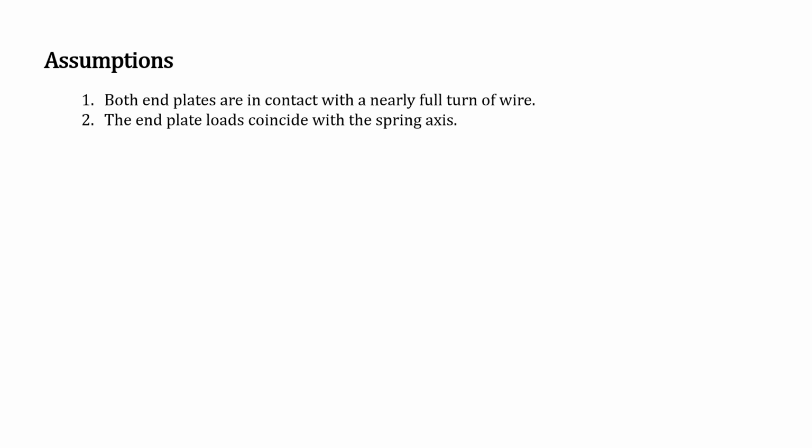So first, as usual, we have a few assumptions. First, both end plates are in contact with a nearly full turn of wire. The end plate loads coincide with the spring axis, so we don't have to deal with any offsets. Yeah, so moving on to actually solving the problem.